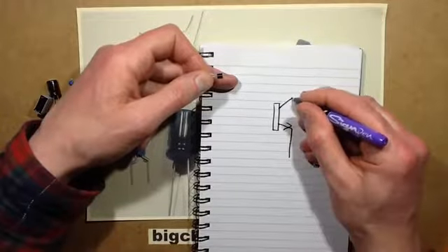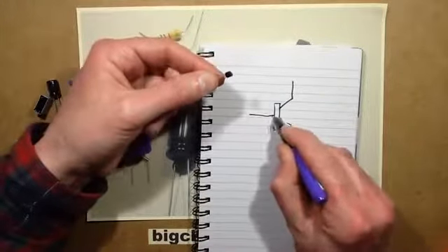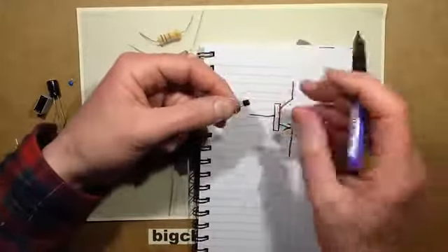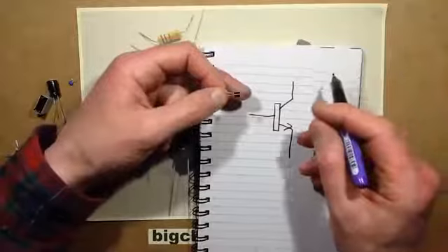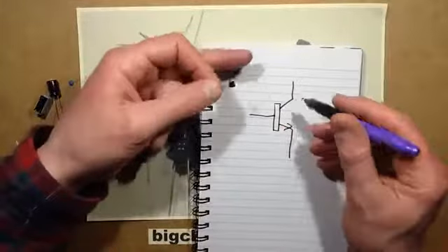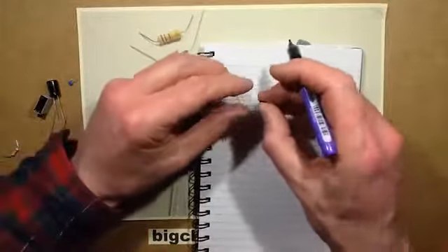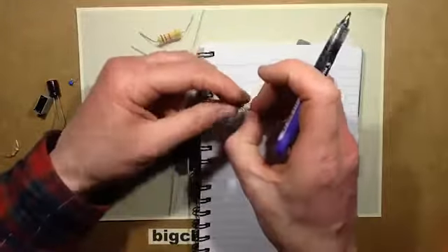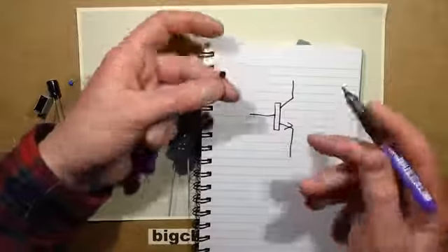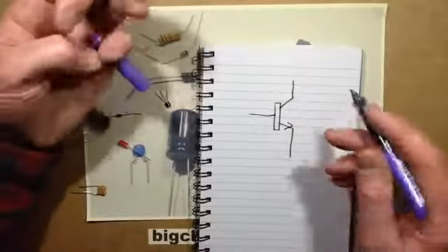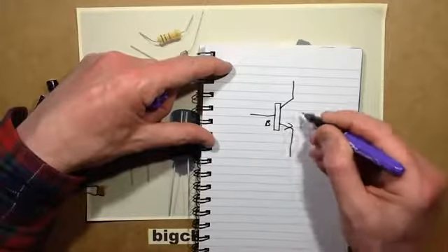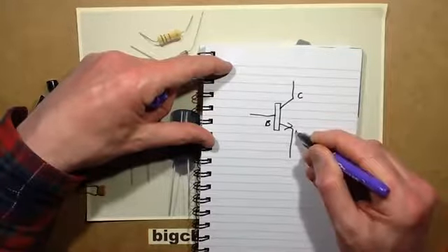You get 3 pins, and if you ever want to find out what the pinout for your transistor is, if you're not 100% sure, just go on Google and type its number in, like 2N3904. Google it, look for images, and you'll find pictures of the transistor with the actual pin designations printed under them. It just makes it very easy to find data like that. So it's got 3 pins. It's got the base pin, the collector pin, and the emitter pin.